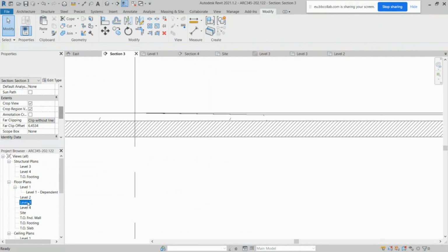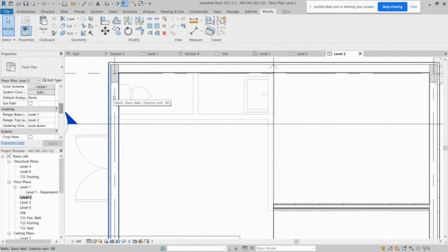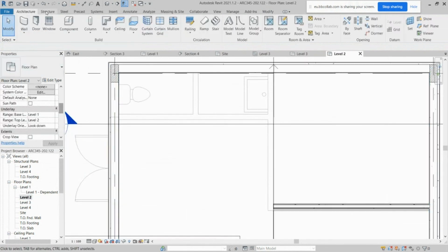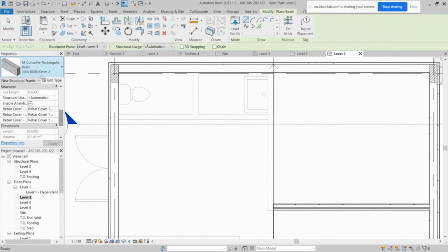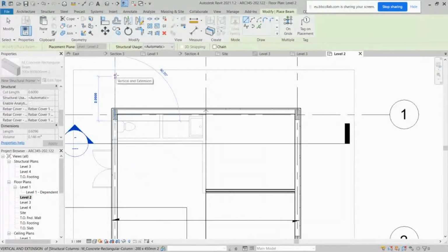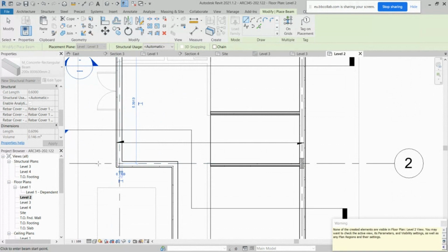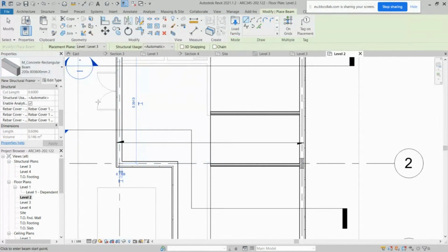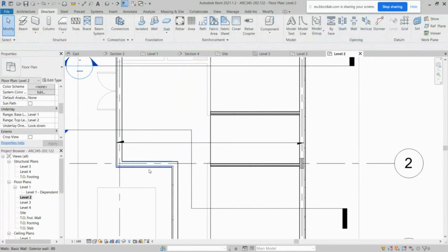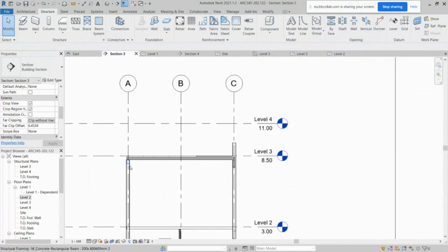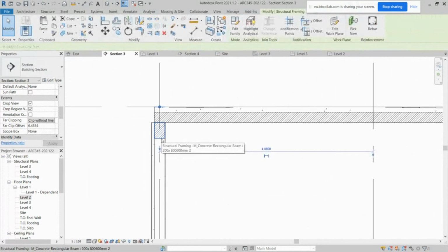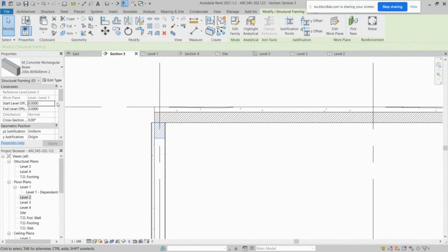So I can just do this one more time. We go to level 2 here, and I would construct another beam. I pick the right one, and of course you have to specify what level, and since we specified level 3 before, that's why level 3 is shown to me. Then I can come here and draw my beam. It doesn't have a column here, but it has to connect to a column. That is my other beam. I did not shift the location for it, so I can come here and shift this to -0.3, so that it starts right behind the slab.